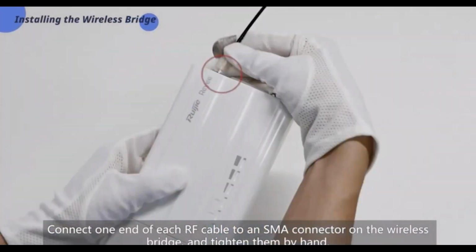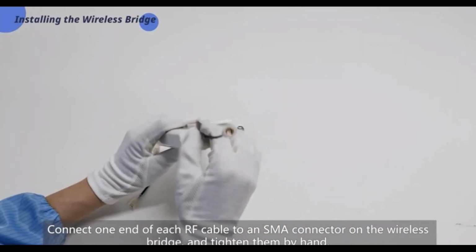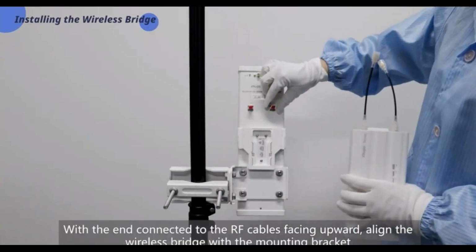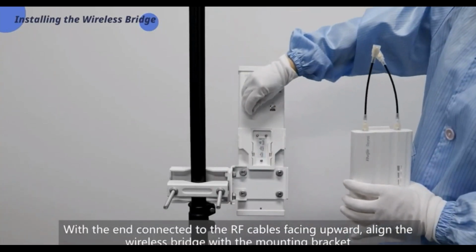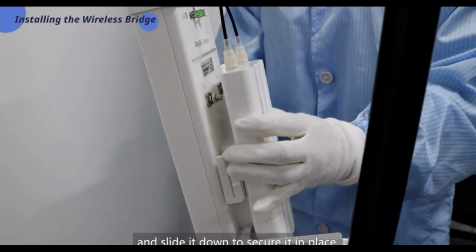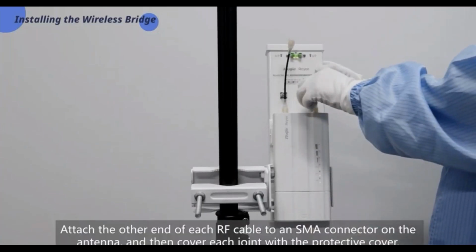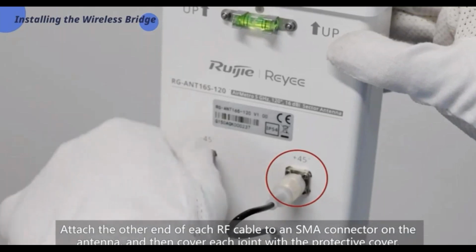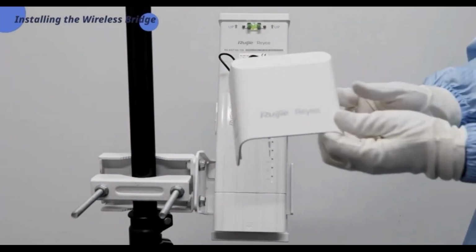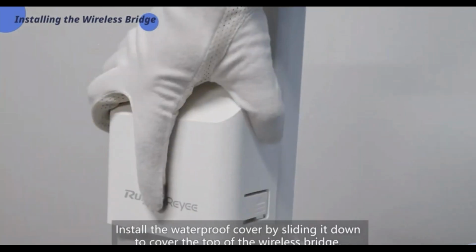Connect one end of each RF cable to an SMA connector on the wireless bridge, and tighten them by hand. With the end connected to the RF cables facing upward, align the wireless bridge with the mounting bracket, and slide it down to secure it in place. Attach the other end of each RF cable to an SMA connector on the antenna, and then cover each joint with the protective cover. Install the waterproof cover by sliding it down to cover the top of the wireless bridge.